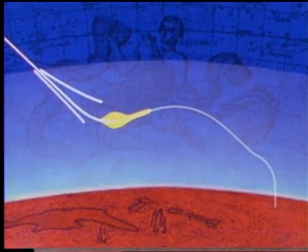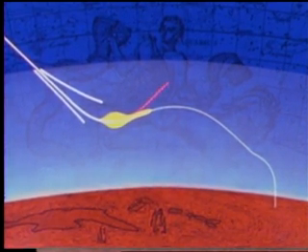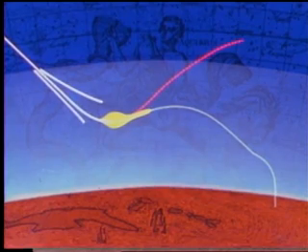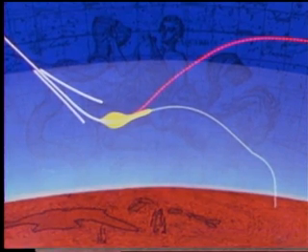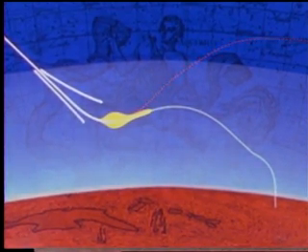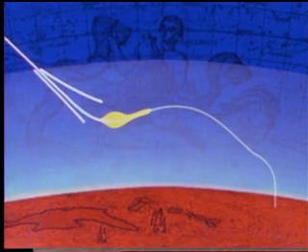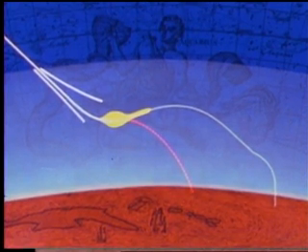That is, too much lift-up could put the spacecraft and crew into an orbit that would last beyond the lifetime of the command module systems. Too much lift-down could take the spacecraft and crew beyond the stress and heating rate limits and result in destruction of the command module.